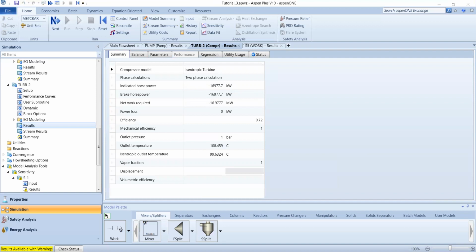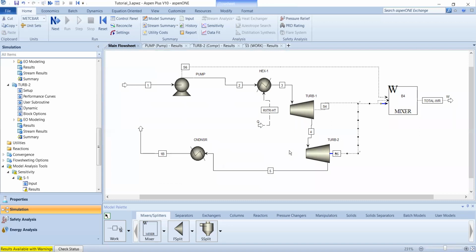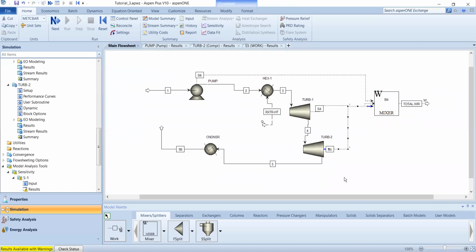Finally, what's the total electrical efficiency of the final power plant? Okay, so what's the total electrical efficiency? Power produced divided by total energy input. Okay, so power produced over total energy input. Let me have a look here. So if I look at the system just as a closed system, if I just draw a box around this, the energy input is this guy, which is 200 megawatts.